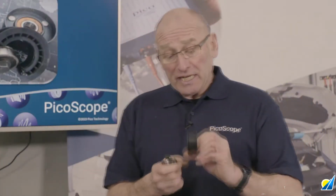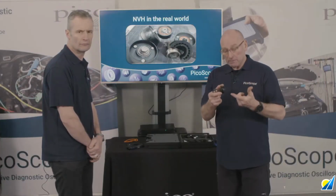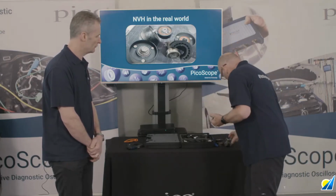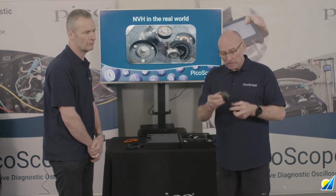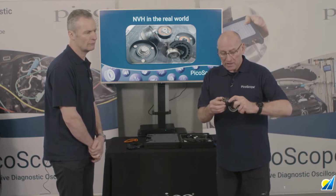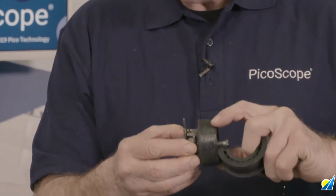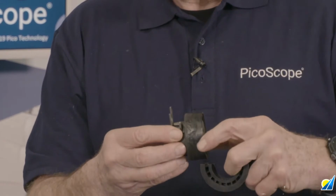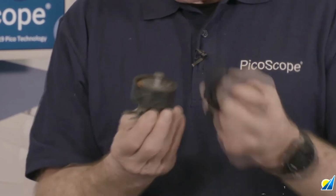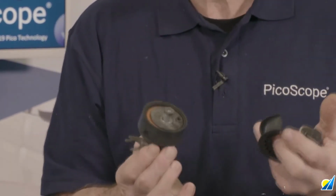Because we'd lost the guide, the belt was able to drift and come in conflict with the timing case cover and the back of the engine, separating part of the belt material. And that belt material then embedded itself on the tension pulley. And you can see here that there are indiscriminate lumps of rubber, is the best way to describe it. Some are more aggressive than others. Now, my conclusion to this is we've found the cause of the problem.